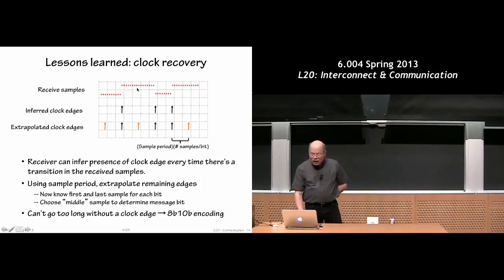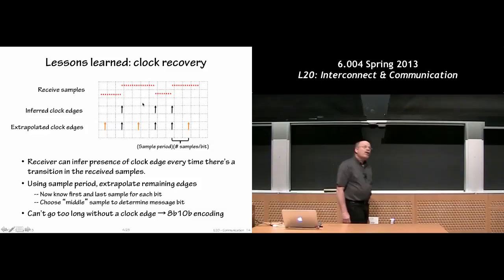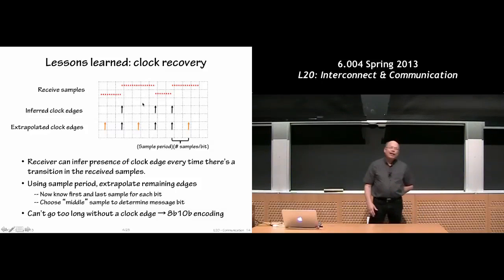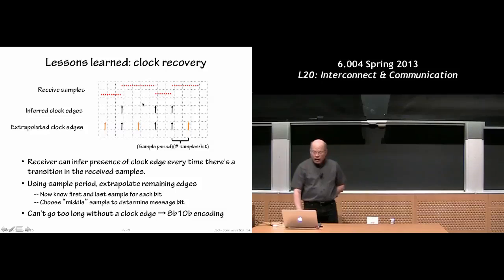It turned out there was not a transition here because we were transmitting 1 in both cells. But I can, so long as I have enough transitions, and in fact, we come up with these careful encodings, like the 8B/10B encoding that you learned about in 602, or will learn about in 602, that guarantees enough transitions that this clock inference mechanism works correctly.